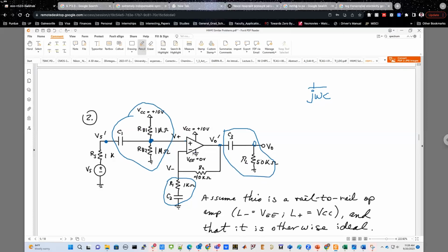But now just look at this point: the RC circuit that you see marked over here is connected to the positive input of the op-amp. There is another RC circuit eventually connected to the negative input, and another RC circuit connected at the output side. So there are 3 different RC networks over here. If you try to find an exact solution of this entire network, let's say you are trying to find the exact voltages at every point, it makes your life very, very hard. As circuit designers, you would always want to assume certain simplifications. What kind of simplification do we assume generally here? Because these RC circuits are connected at 3 different points of the op-amp, one is connected to the positive input, and you already know that the positive input is sort of decoupled from the negative input for the op-amp. There's no relation between the positive and negative, except for the fact that you have the virtual ground property. So generally, this is connected at a different point, this is at a different point, this is at a different point. You'll consider them as isolated RC networks.